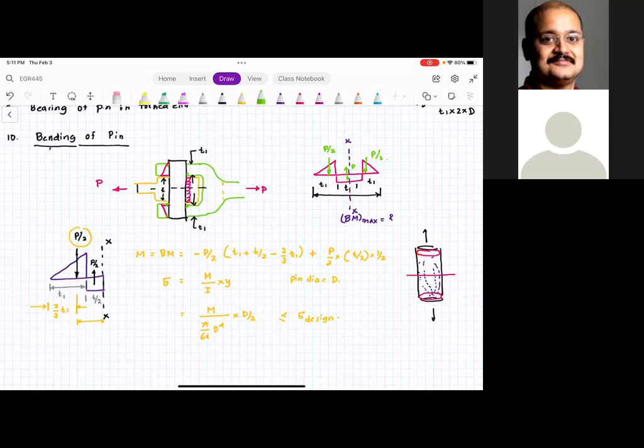Once you do it, you will realize that basically at the contact points, the stresses are significantly higher. And those contact stresses are called Hertzian stresses. Because of those extremely high localized stresses, there is pitting. The material gets removed, a teeny tiny amount.